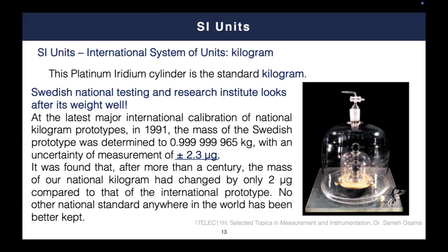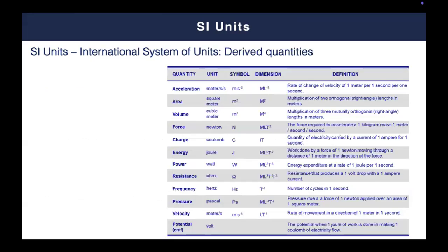I think I asked you a very simple question: okay, the temperature sensor is now showing 22 degrees Celsius. Why should I trust that the temperature is 22? So you have to implement a standard calibration step. One of the very important items we are going to consider in this course is how to calibrate your circuit or your sensor, because this is a very fundamental process for any sensor.